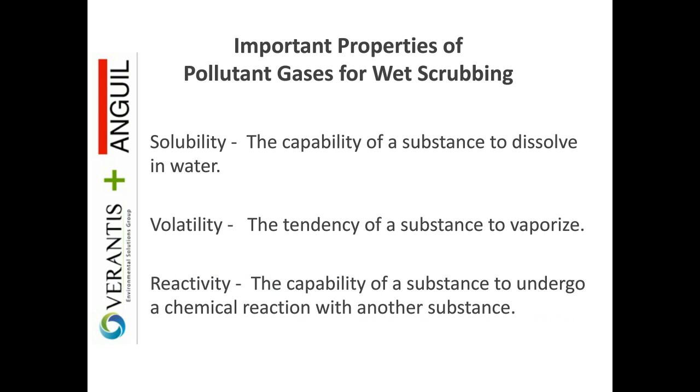So when we look at a wet scrubber design, there are really three core considerations to make when we look at a given pollutant that we want to control: solubility, volatility, and reactivity. These can be used sometimes alone and, in many cases, in combination to effectively wet scrub a compound.